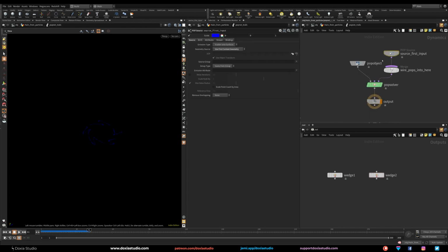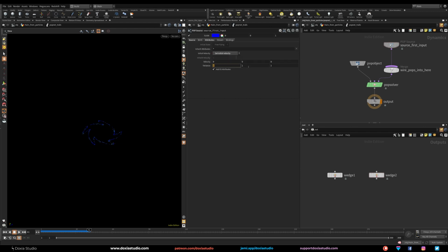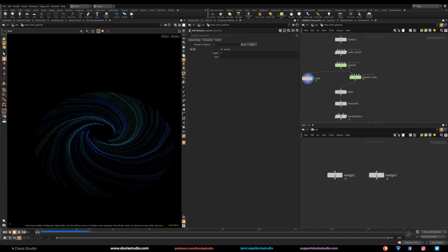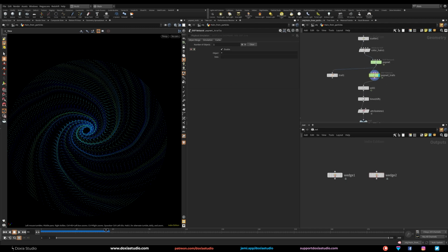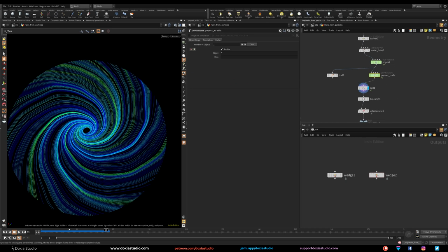And here we just need to tell it: emission type, use all the points, okay? And don't use anything else. Don't add velocity and don't use anything. So here, let's set initial velocity. Let's clean our variance, okay? So don't add any velocity for these created particles, and don't add ID attributes, because we need to use those ID attributes to create our polygons, right? So let's see. Now we have our trails, and if I check our add, now we have our splines.